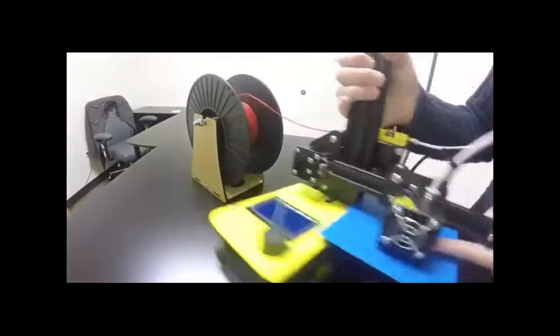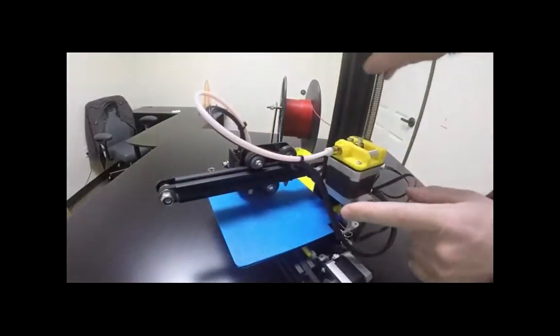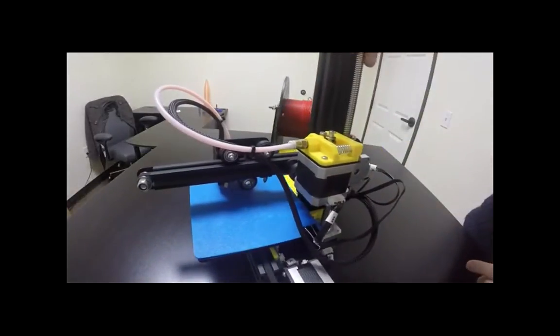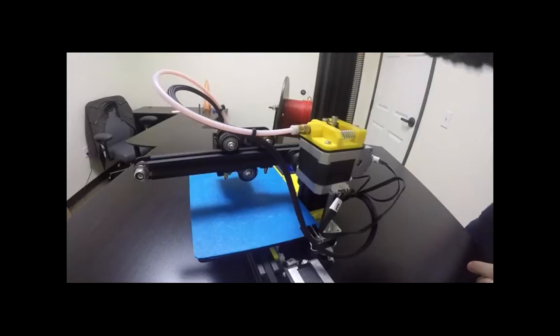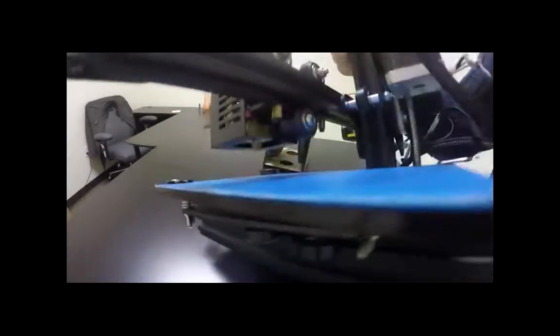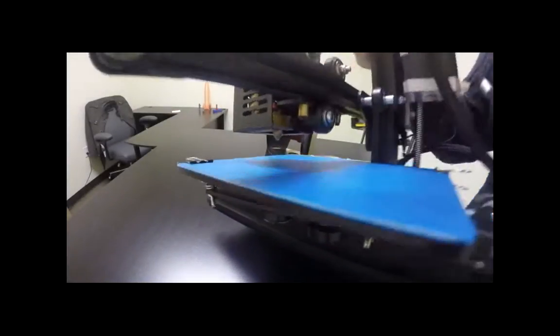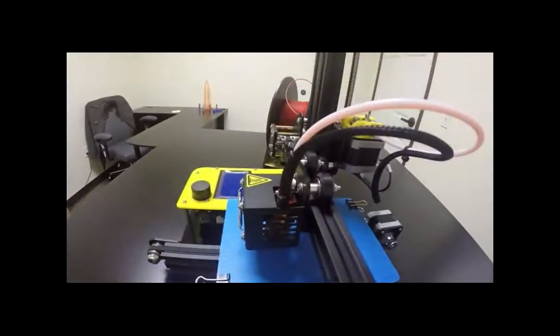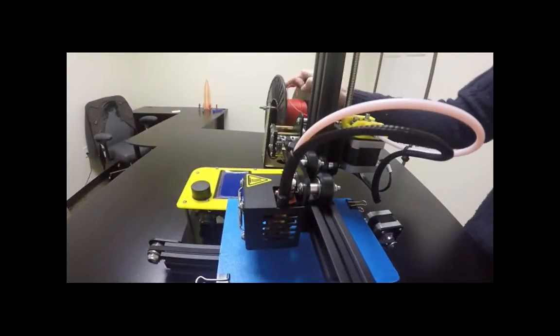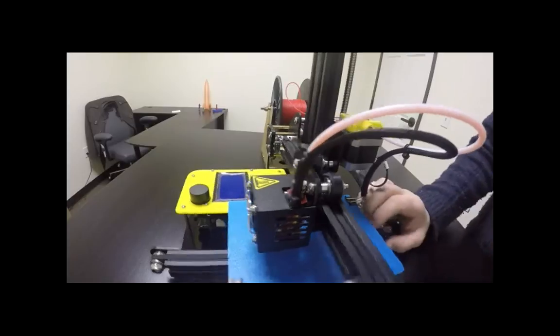That's on there. And if you can see it, you can twist this right here and lift it up a little bit, if yours is pushed all the way down to the bed. And you can see the nozzle right there. Because you want to have a little bit of a space, maybe about an inch between the nozzle and the build plate, so you can see when you push the filament through.